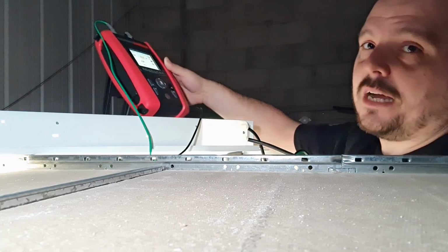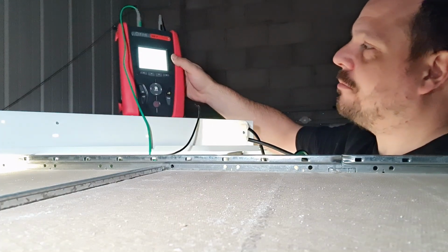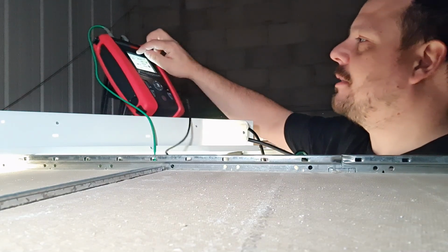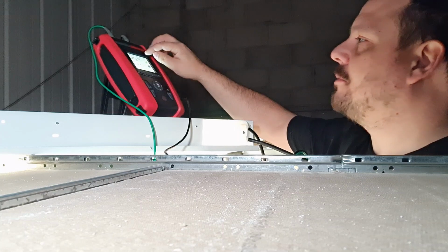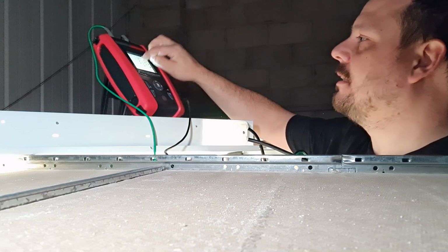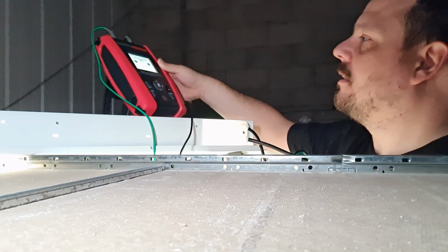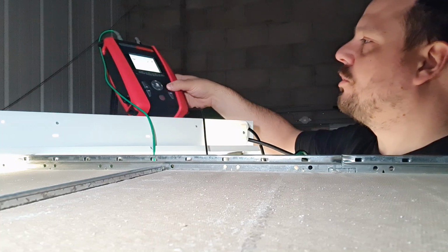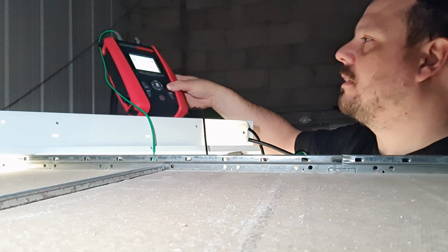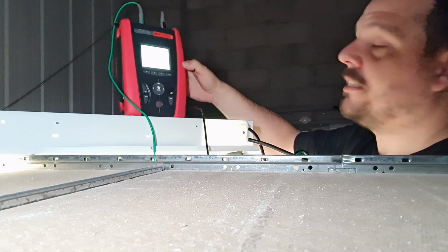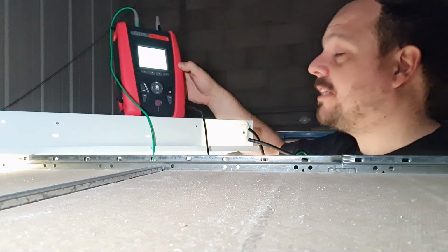It's given me a thumbs down on the test because I've left it set up for a 100 amp fuse, so that's a feature of that. Let's redo that because that's quite interesting. If I change it to an MCB, type B, and change it to a 6 amp, save all of that, the test set should now give us a different result on the screen. So you can see there it's given us a green thumbs up. So that's really quite clever.